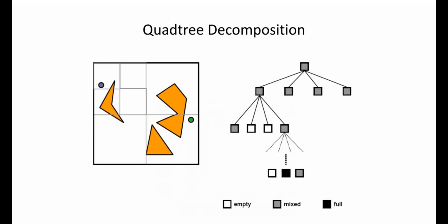And so our algorithm is just as I mentioned, where we look and see how much of my cell is full. This is a threshold that you can set yourself, where you consider something completely full or partially full or empty. And if something is partially full, you just split it. And if it's empty or full, you just keep it as is. And so you can represent this as a tree. And you can basically just keep going as far as you want until you maybe hit some kind of minimum length scale for each of your cells.